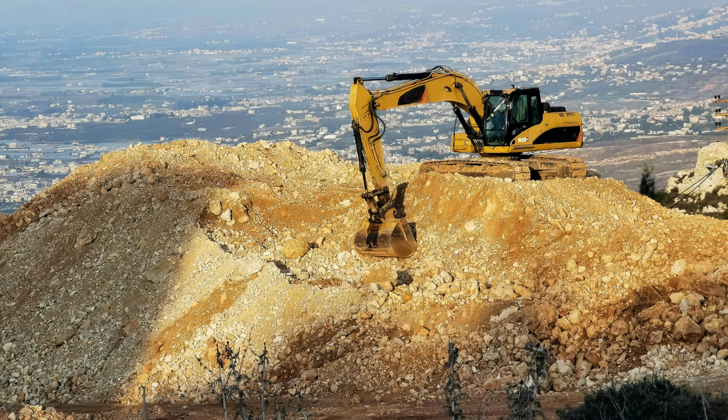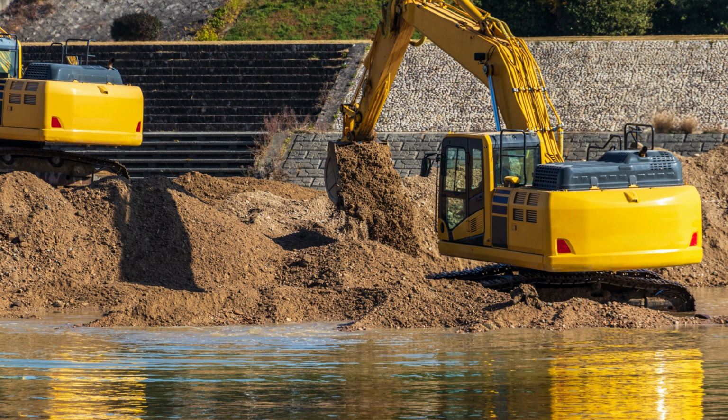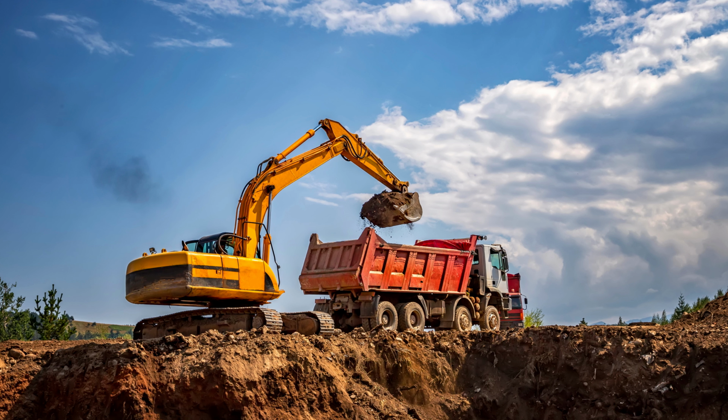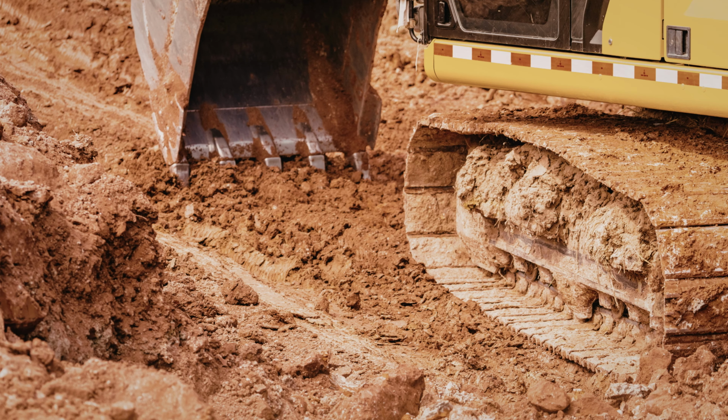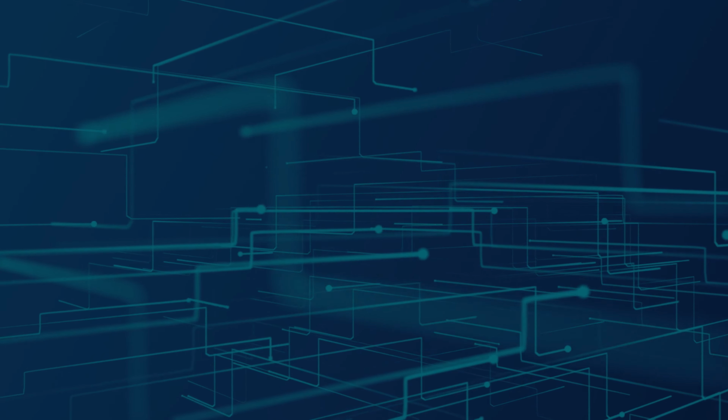The stability margin is determined by comparing the resisting moment generated by the machine's weight and counterweight with the overturning moment created by the bucket load and its horizontal distance from the tipping axis. By evaluating these margins under various load cases, engineers can ensure that the excavator maintains adequate safety factors and remains stable even under demanding operating conditions.